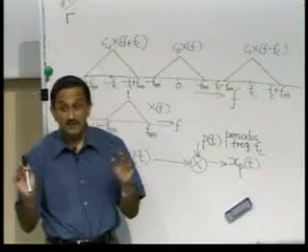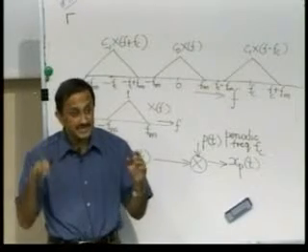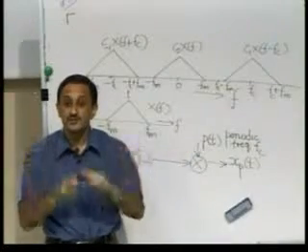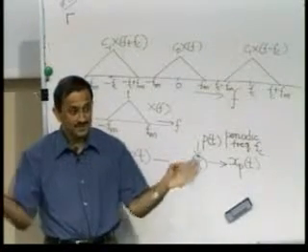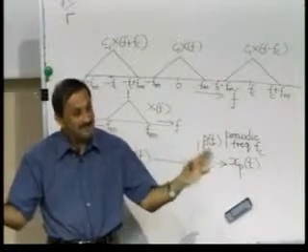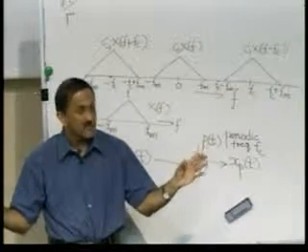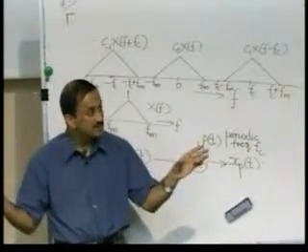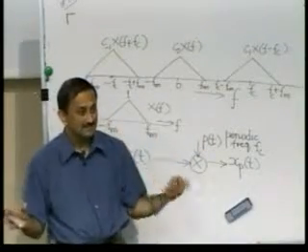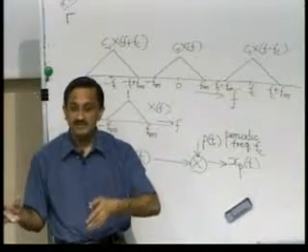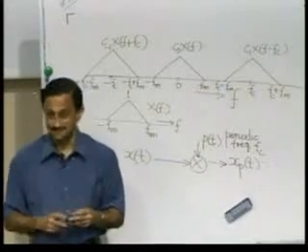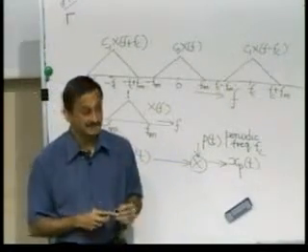And recall that since my original gating pattern is a real function, C3 and C minus 3 would be complex conjugates. So, when I put a band pass filter symmetrically on both sides of the frequency axis, the spectrum would also remain conjugate symmetric. So, it would indeed give me the modulation of the original waveform x(t) with a carrier of frequency 3 times Fc. In fact, the same principle can be extended to get a carrier which is any multiple of Fc. So, there are two advantages that we have gained here.